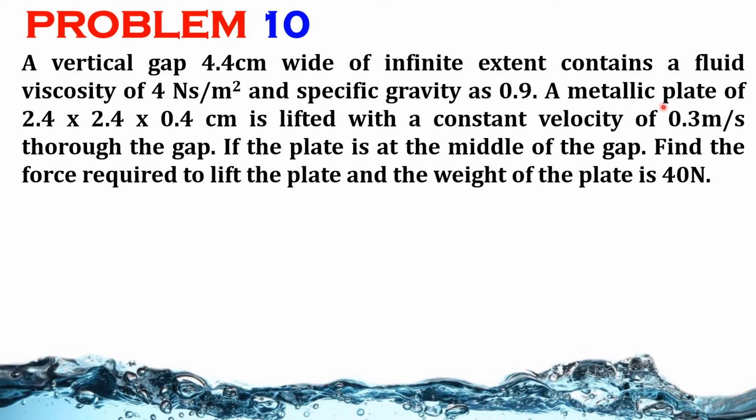A metallic plate of 2.4 by 2.4 by 0.4 centimeter is lifted with a constant velocity of 0.3 meter per second through the gap. If the plate is at the middle of the gap, find the force required to lift the plate, given the weight of the plate is 40 Newton.